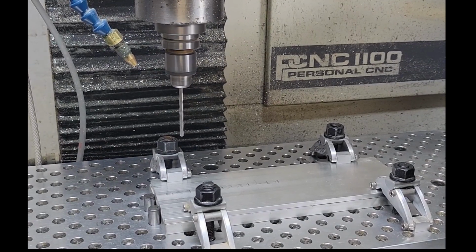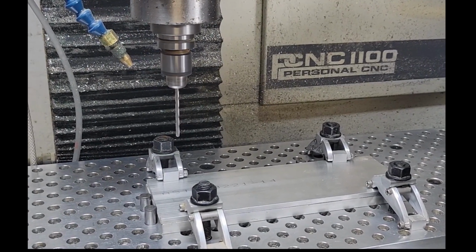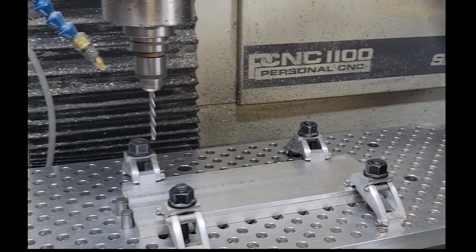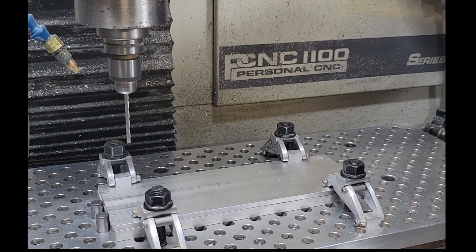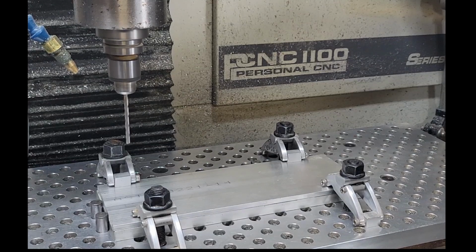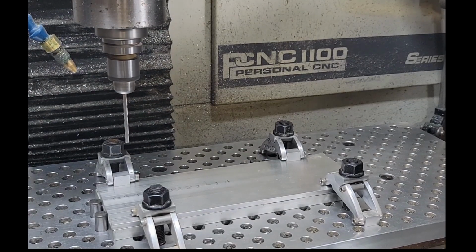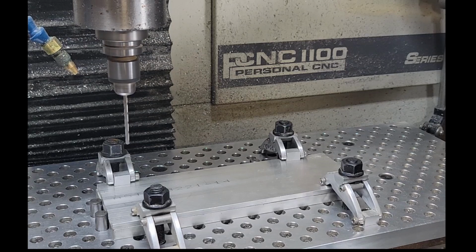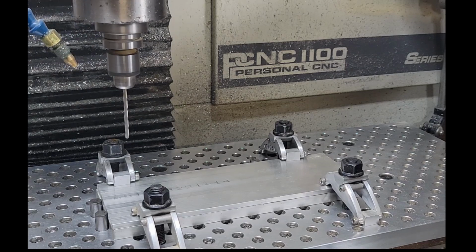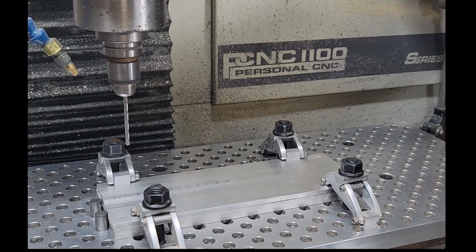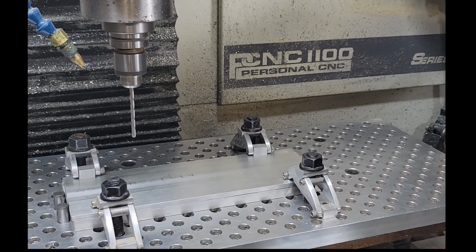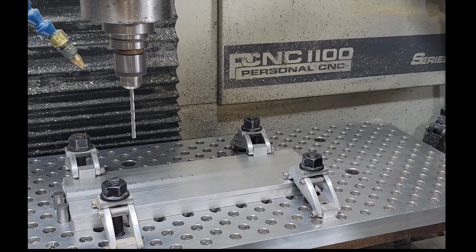This is the peg drill cycle. It's going down, then it comes back up, it ramps back up. Now this is the peg drill cycle, but everything is up in the air just to prove that the program works. It's running good, so I can confidently now go back and put the offset down and run the program. Say now, okay, we're ready to go and run the program in, and I can start ramping up the feed rates and stuff. I know it's running good.